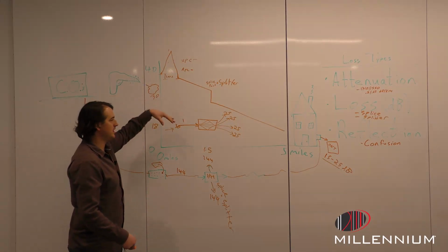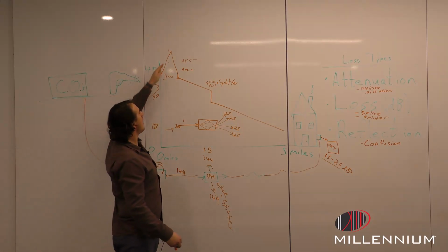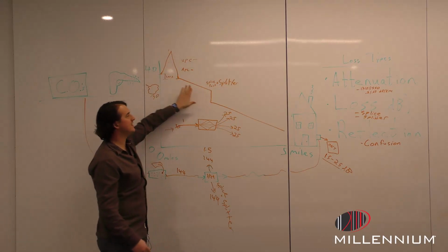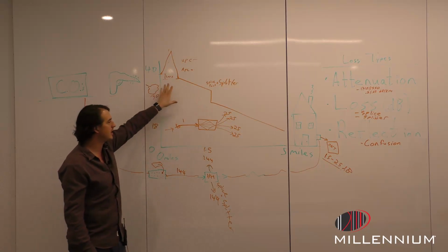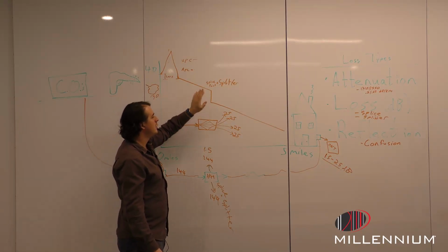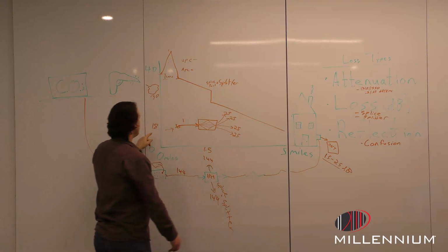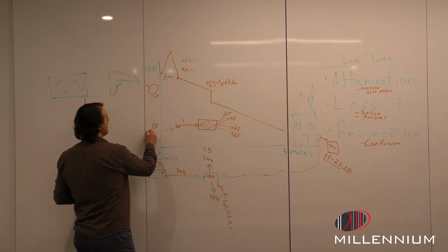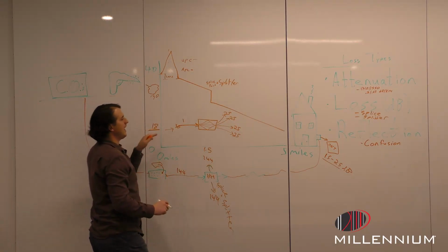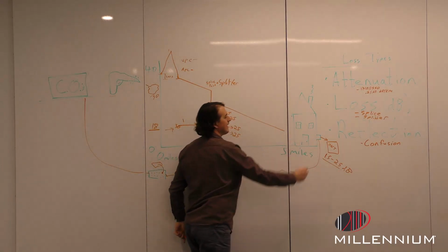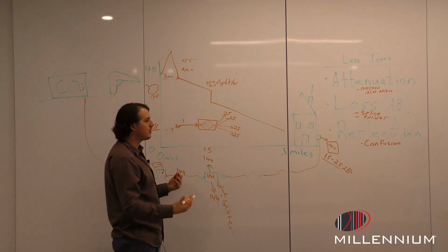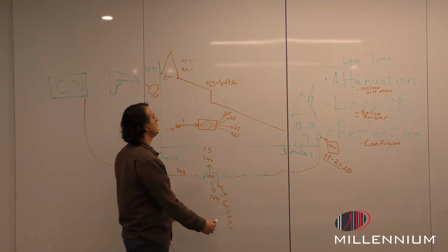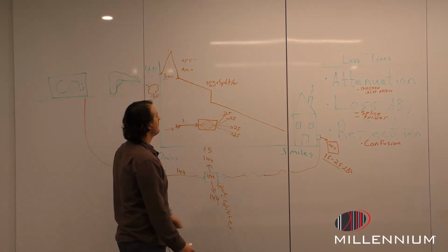So they get out the OTDR. They shoot their OTDR, it sees all these events, and these events can be very planned out, highly engineered. This is our light budget we're looking at. But remember, it's going to be engineered so that it works. So right now this was engineered so we'd be at 18 decibel when the light got to that ONT. Perfect, these people have internet. But they're calling, complaining, what's going on? Get out the OTDR. So we shoot the OTDR.